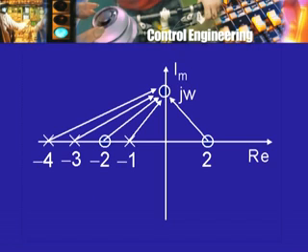So, we had 3 poles and 2 zeros. Suppose the loop transfer function was like this. Now, what will be the variation of GH(j omega) as omega varies? Once again, qualitatively, as far as the two limits are concerned, omega tending to 0 and omega tending to infinity, it is possible to work out what the limits will be.